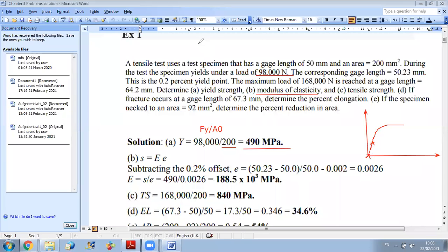the yield point. And they said that the yield point was estimated based on the offset method, the 0.2% offset method. What is this method? This method considers a point epsilon equal to 0.2%. So it takes epsilon equals 0.002, which is very close to 0.